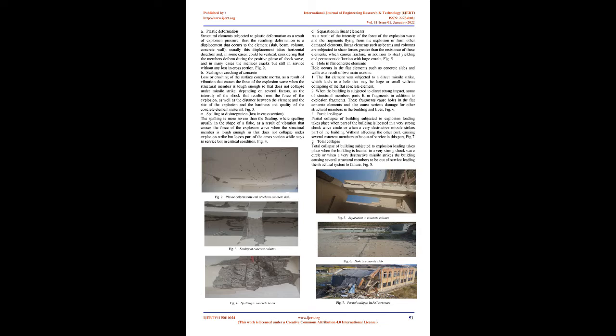Plastic deformation. Structural elements are subjected to plastic deformation as a result of explosion pressure, and the resulting deformation is a displacement that occurs to the element: slab, beam, column, or concrete wall. Usually this displacement takes a horizontal direction and, in some cases, could be vertical, considering that the members deform during the positive phase of the shock wave. In many cases the member cracks but is still in service without any loss in cross-section. Fig. 2.